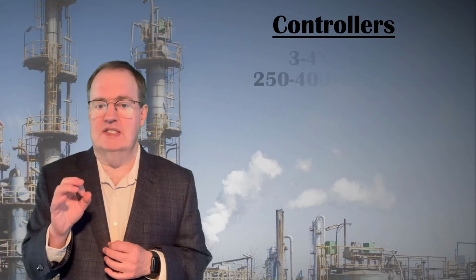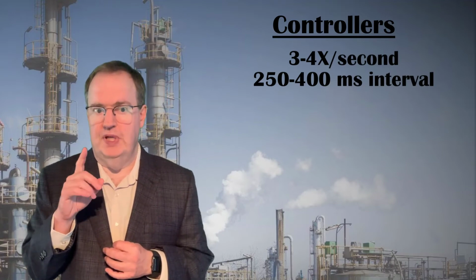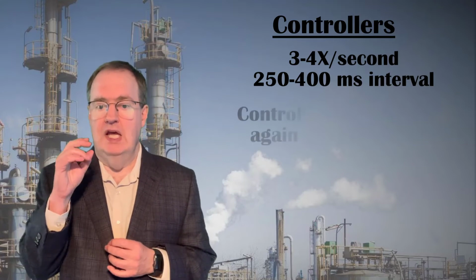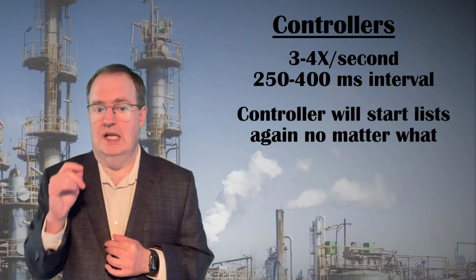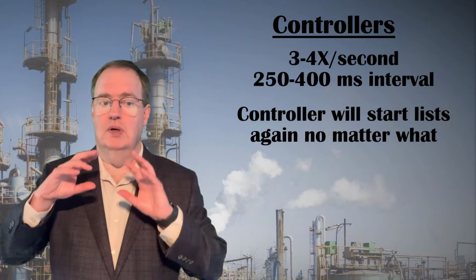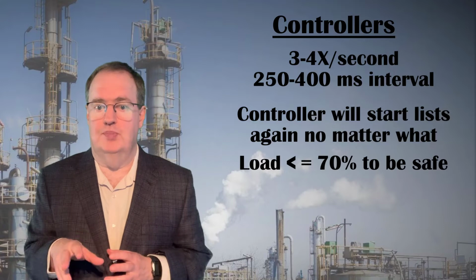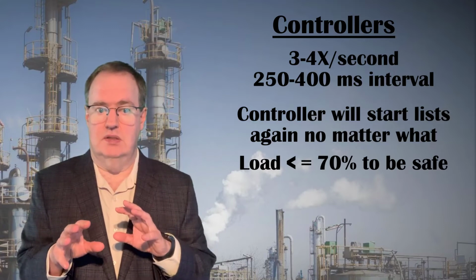We need all of these tasks to be performed 3 to 4 times a second, or performance will be noticeably slow, so once every 250 to 400 milliseconds. If a controller does not finish its list before it is time to start again, it will leave the last items on the list unaddressed. So it is vital to never load a controller more than about 70% of its capacity under normal operation, because we do not want to run out of capacity in a crisis.